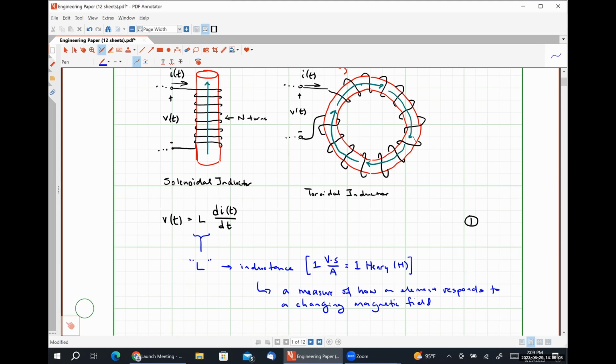The material that's inside the coil also tends to have some effect on the inductance. Generally speaking, inductors are wound on ferromagnetic cores. It's a material that is very easily magnetized because that internal magnetization tends to enhance the externally generated magnetic field, giving you a larger amount of what's called magnetic flux.